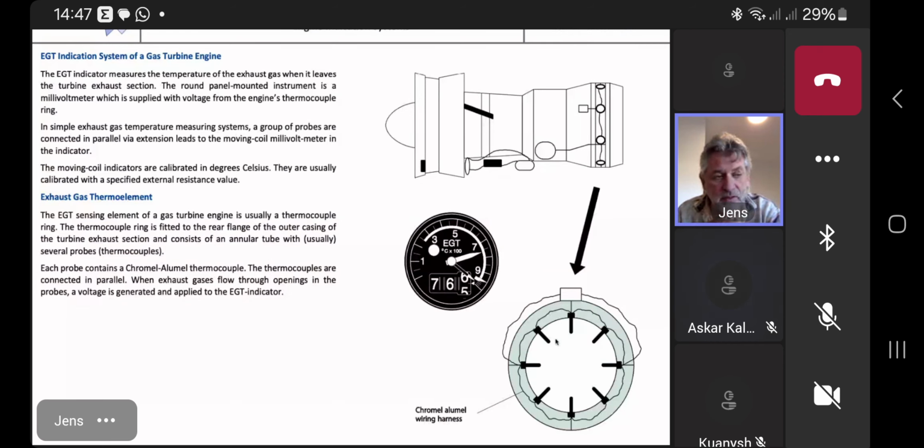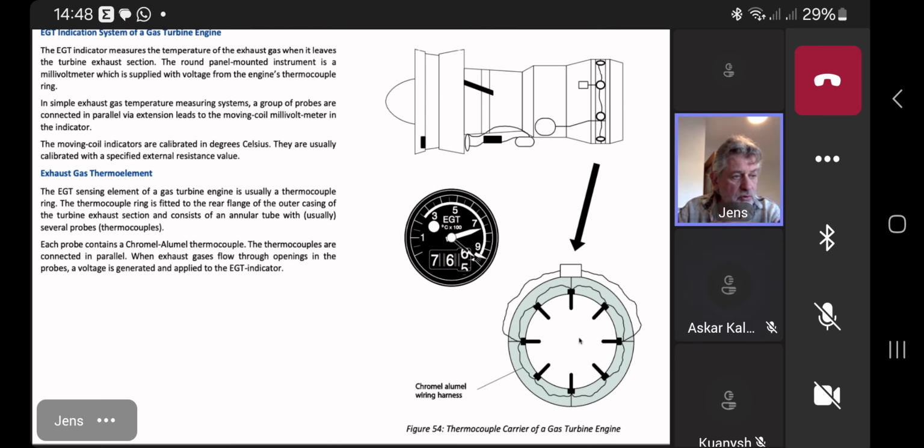They're just some little metal things. As far as from my history, whenever they were not functioning, we just scrap them and install new, because they're not that expensive. Of course, what we have to make sure is, as you can see here, the first thing important is we do not need an external power supply, because those chromel-alumel thermocouples produce their own voltage. So it's an advantage. You don't have to provide them with any power supply, which is also nice.